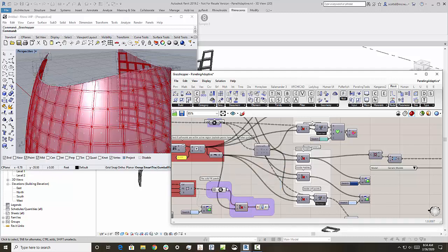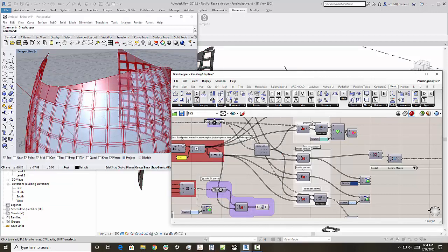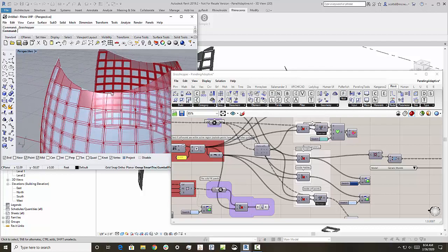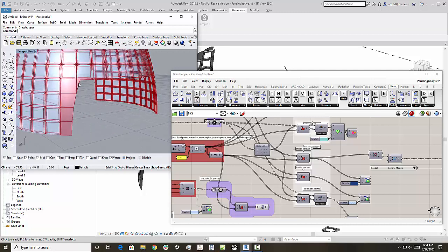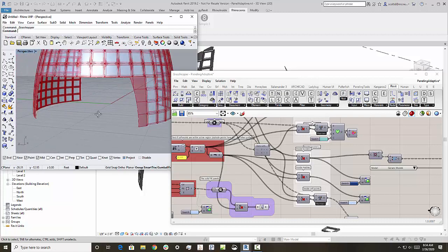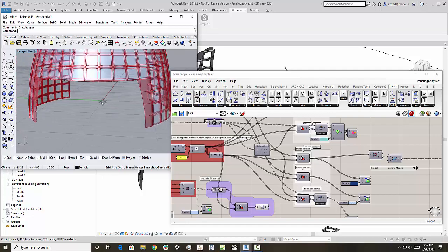let's enable that. Turn off the preview. What I've done is taken the surface area underneath those panels that are partial, and then trimmed them with Grasshopper, and then added them as direct shapes in Revit. So from Grasshopper I actually made these trims, and now I have full solid panels at those edges, as if it was some sort of trim for this opening on the building level, and some sort of solid condition as we get to these more complicated shapes that we want to deal with.